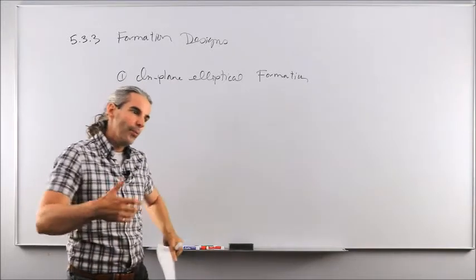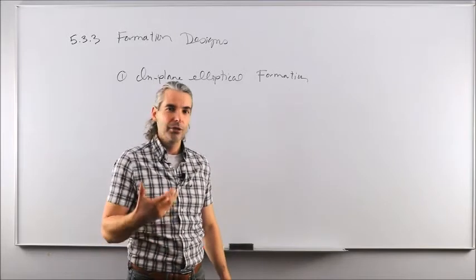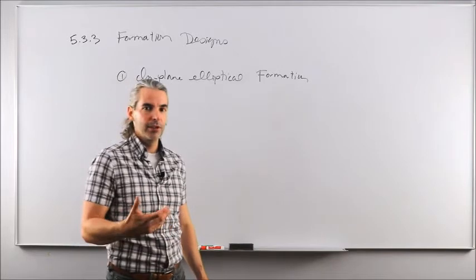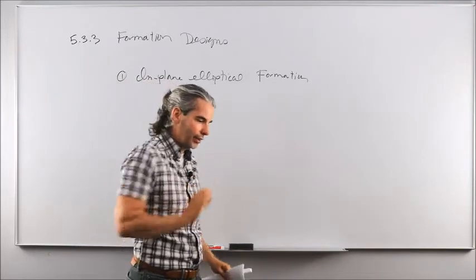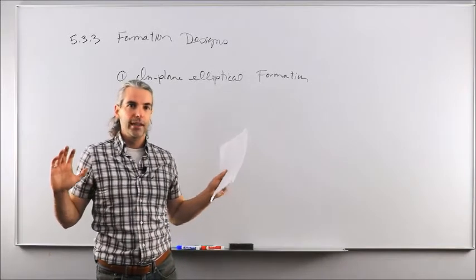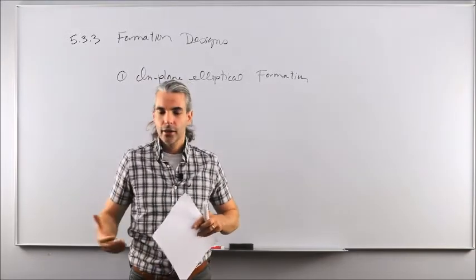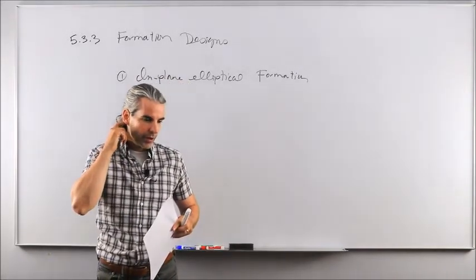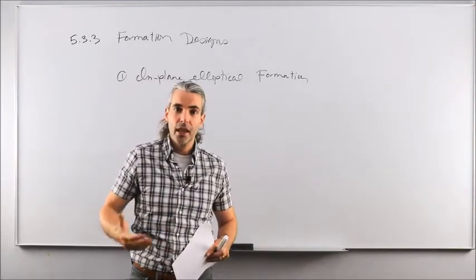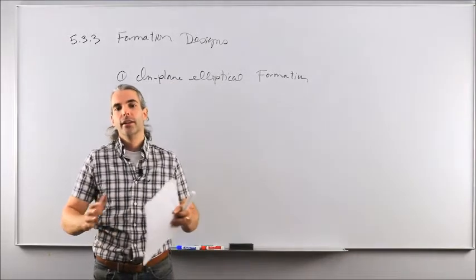and therefore those initial conditions would almost generate the ellipse we were looking for in the first formation design. But if you want to maintain that ellipse over, say, 100 orbits, you need to actively correct the trajectory to maintain that ellipse, because passively, just by selecting the initial conditions and being hands-off, would generate that ellipse for a couple of orbits, but after time, the perturbations like drag would mean that one of the two spacecraft would have its semi-major axis changing more rapidly than the other one, and therefore the orbital energy won't be the same anymore, and thereby it would start to drift.